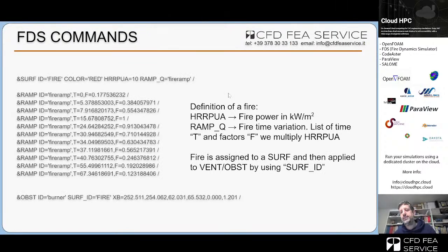There are few things which by default BlenderFDS doesn't do, or it can do in a manual way, and at least as far as I suggest is to work directly on the FDS file exported by BlenderFDS. So the first one: in the regulations for fire prevention, usually you don't have to apply a constant HRR curve, but this curve is variable in time.